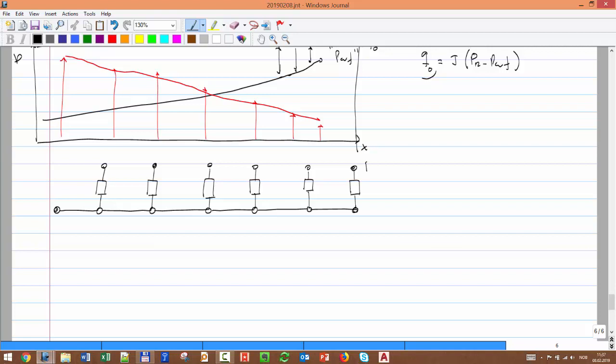So here I have reservoir pressure. That's my IPR equation in each one of these boxes, and then I should add one more box where I have my pipe. Okay, my pipe PR equation.